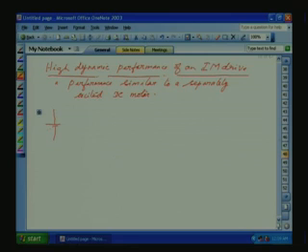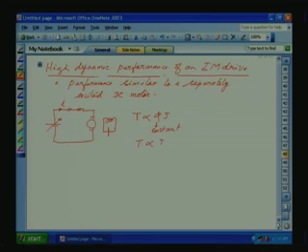For a DC motor, we control the voltage. You have the armature resistance and then the back EMF from the motor. But the field we control separately, and the field is kept constant. So the torque is proportional to phi into I, where I is the armature current. Phi is constant, so T is proportional to I.